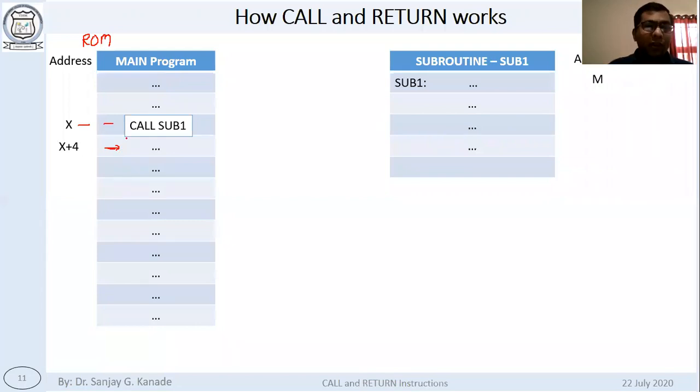Now, when this call instruction is getting executed, what will happen? First thing, the stack pointer will increment. You see here, STKPTR means stack pointer equals stack pointer plus 1. Whatever the value of the stack pointer was initially, that will first increment.